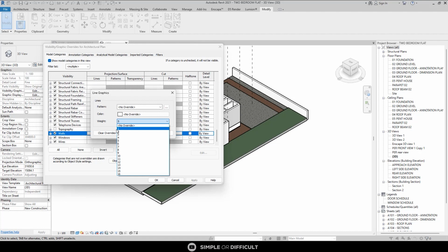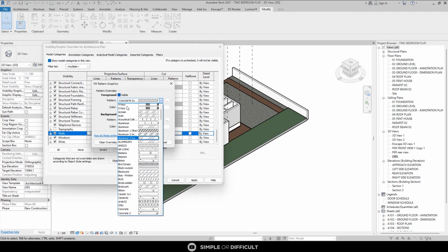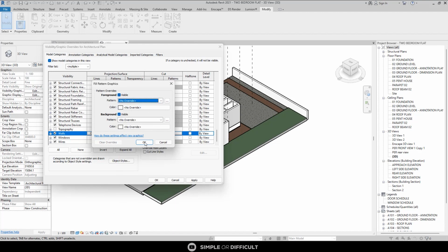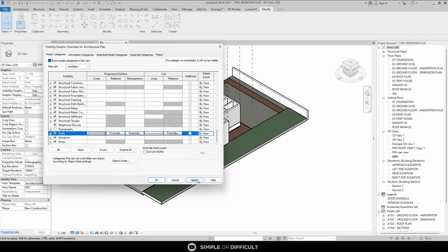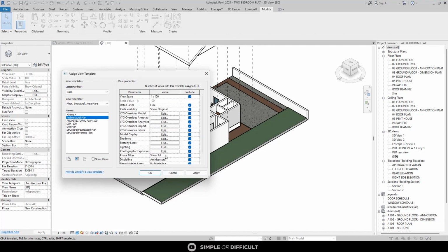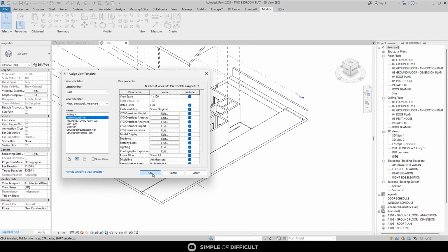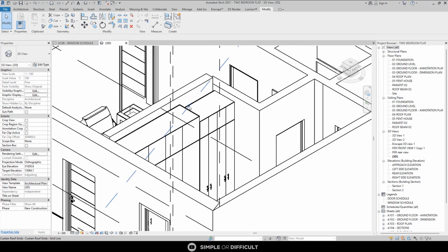Okay, remove this. I don't want that. All right, come over here, set this one also to be at 1, and then hit apply. Now when you come here, you see the thin line is turned off, and you can see everything is the same width.